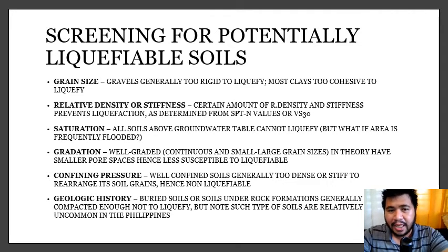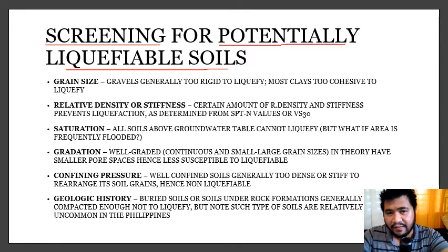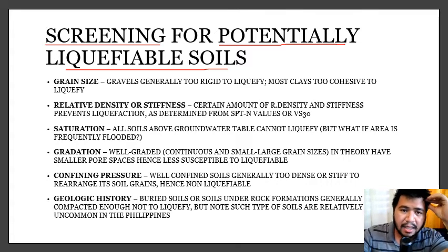We do screening before we do the analysis, and the purpose of screening is to basically identify the soils that can potentially liquefy. If they can potentially liquefy, then we calculate their factor of safety against liquefaction. So this is just step one before we do the actual analysis.